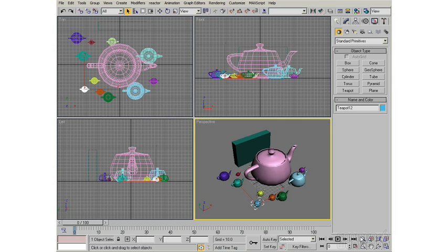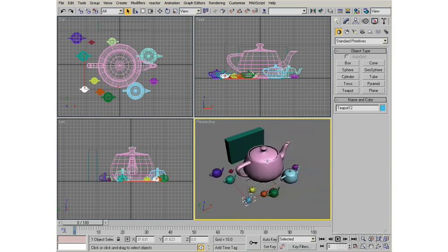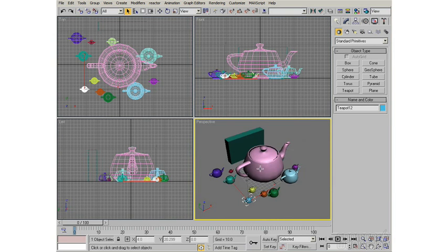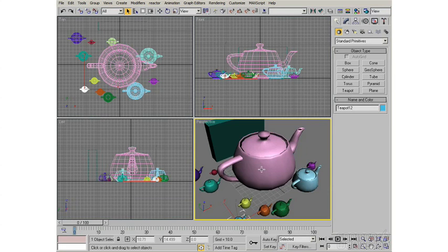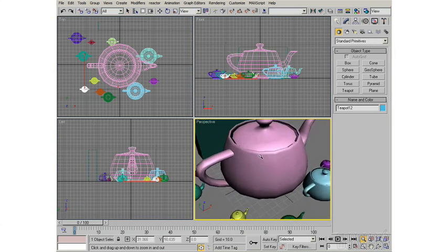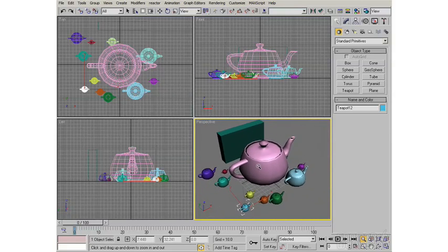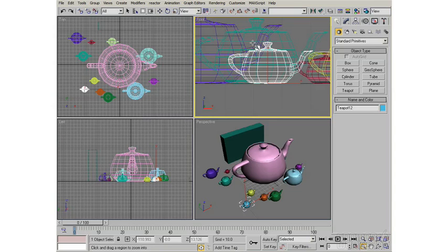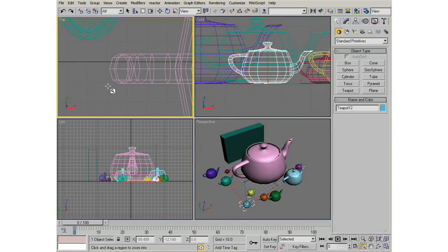You need a few additional ones. That's where down here in the lower right hand corner you have all these controls which pertain to the view. When I'm zooming in or out with the middle mouse button, wheeling in or out, it's not a very fine-grained zoom. So that's where you can come down here and use the little zoom tool to go in or out. That gives you a little bit more control. Right below that, there's a rectangle zoom, which allows you to draw a box in which you can zoom in very specifically to some part.